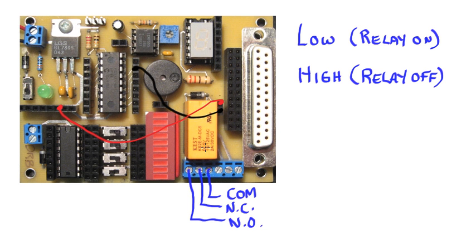To connect the device, we have to observe the current limits and the voltage limits and voltage types for this specific relay. This one can handle AC and DC. With the DC, it can handle up to 30 volts and 2 amps. So we can use any voltage that we want within that range. So let's say we have a motor.